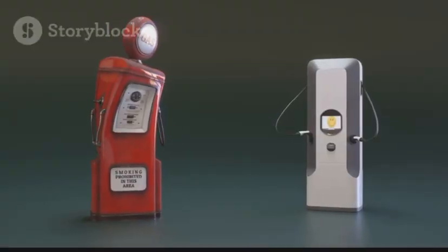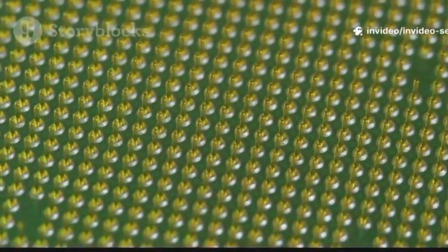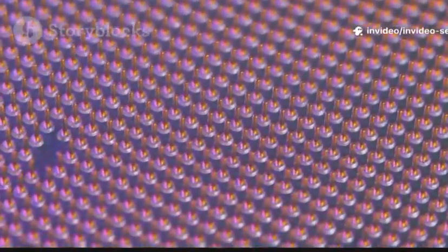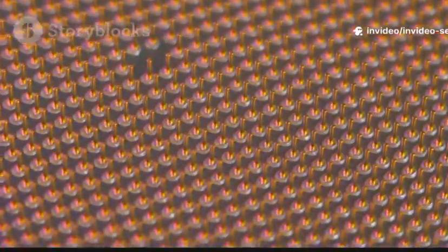The other subtype is called a P-type semiconductor. For this, we dope the silicon with an element like boron. Boron has fewer electrons than silicon. This creates holes, or empty spots where an electron could be. These holes act like positive charges that can also move through the material. In a P-type semiconductor, it's the movement of these holes that allows electricity to flow. It's a different way of carrying a current, but just as effective.